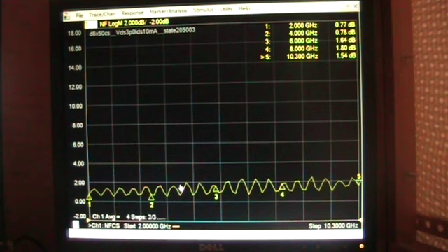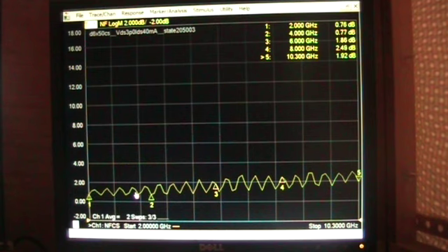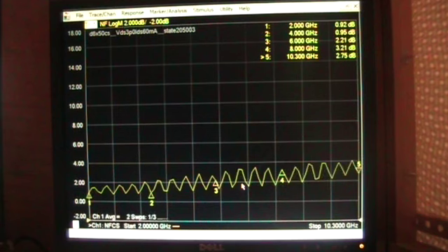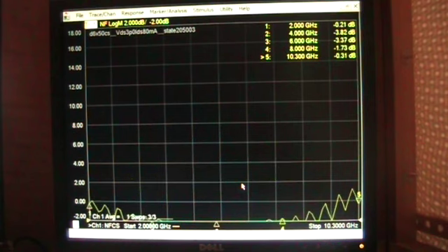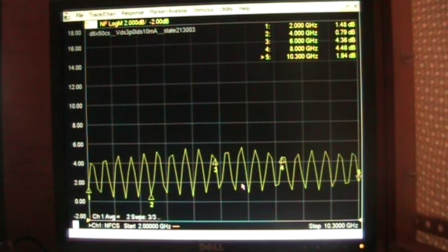It's also a little bit faster if instead of measuring in 100 megahertz steps in order to reveal this pattern, instead we would just measure in 1 megahertz steps. Now you can't see this aliasing, this ripple in the measurements when you do that, so it's harder to convey what the system's actually doing. But it does speed up the measurements quite a bit, and when we're extracting noise parameters on only 1 or maybe even 2 gigahertz steps, it's really unnecessary to perform 100 megahertz measurements all the time.